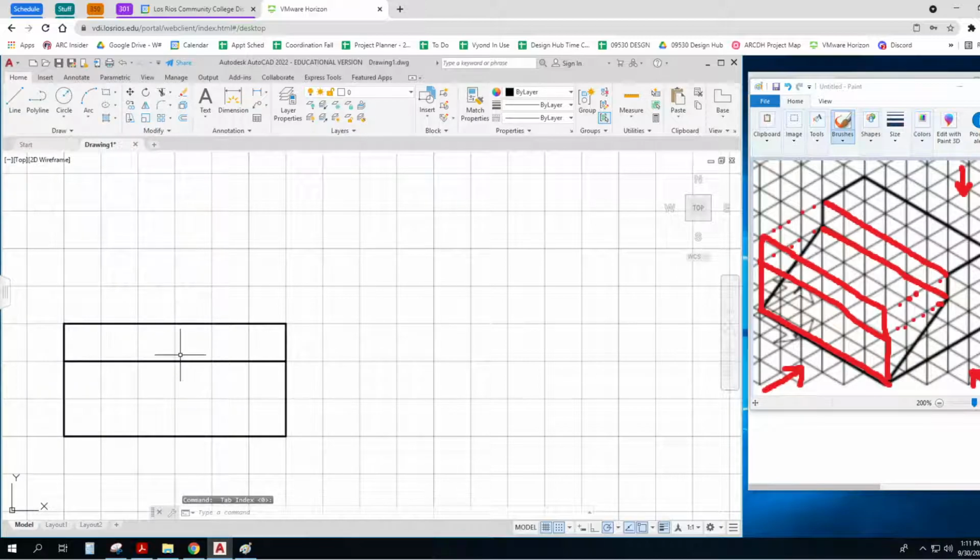So that's what I would see right over here is what I would see in that front view. Now this one's really easy because it is all flat, right? This one I would see over on the right. I'm tracing it right now. So I'd see over 1, 2, 3, 4, 5, up 3, over 2, down 1, and back to the beginning. Now, where do we put that? It's the right side view, so I'm going to put it on the right.